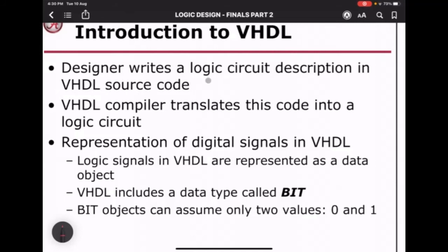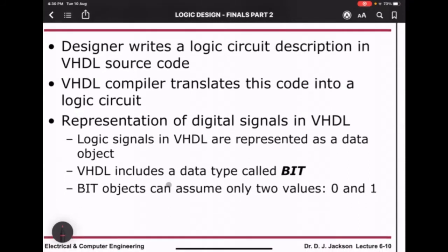So the VHDL is created by the designer. It is input inside the CAD system. The CAD system has a VHDL compiler. When you compile the source code you input, the CAD system will translate this code into a logic circuit. It creates your circuit for you.